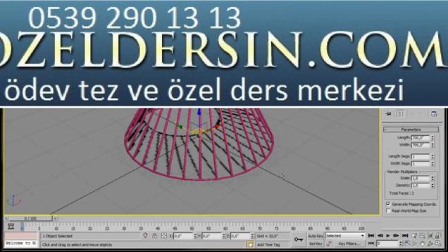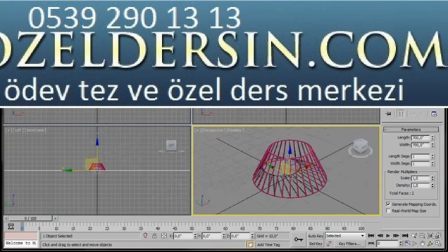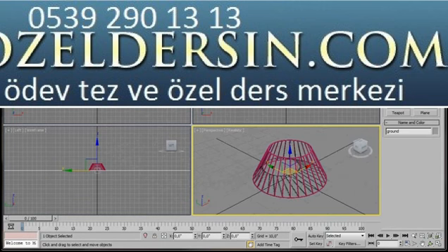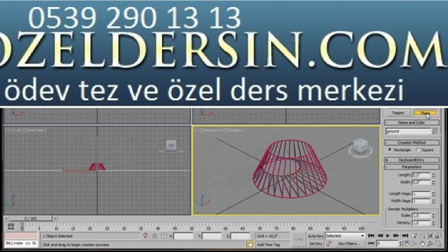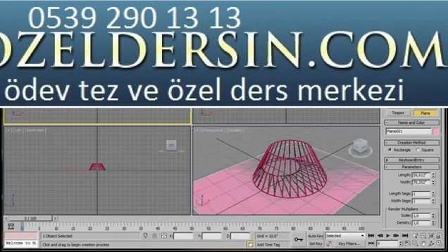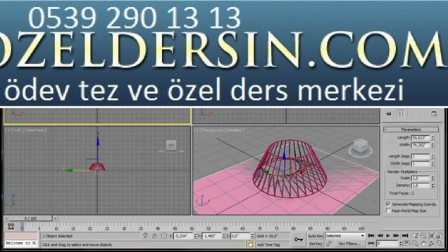Let's go to all 4 viewports. Press Alt W on the keyboard to do that. Now we're going to create another plane as our cloth object, so we'll go over to Geometry and select a plane. Now we can draw out a small plane in the top viewport. Go over to the Modify panel, and first of all we'll change the name. Let's type in lace cloth.